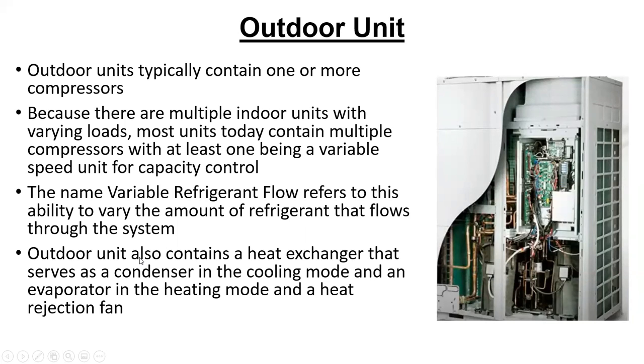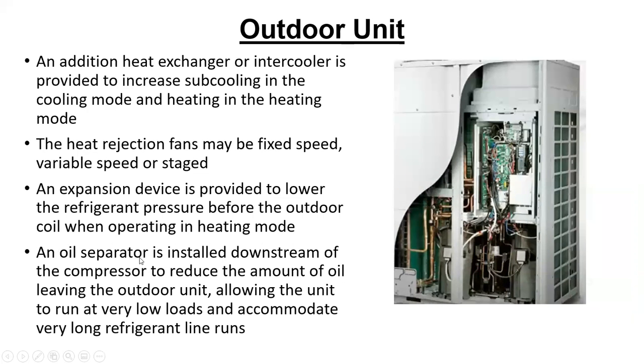And there's also a heat rejection fan. So in that respect, it's like a heat pump. An additional heat exchanger or intercooler is provided to increase subcooling in the cooling mode and heating in the heating mode. So that's for efficiency enhancement. Heat rejection fans: if you're in a cooling mode, that coil outside is being a condenser, and you're going to blow outside air across it and reject heat to the atmosphere.